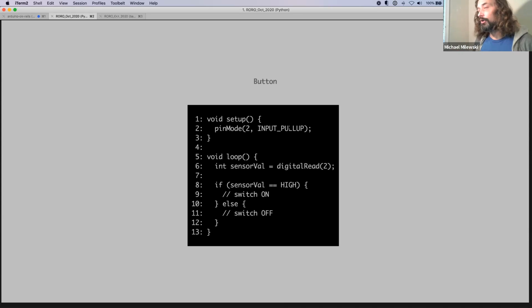To stop that, you want some resistance in there. So the resistance reduces that. In this case, there is inbuilt resistance. So you can really simplify your circuit. So the circuit I've got literally just has a button. It doesn't even have a resistor. It doesn't need that. So that's one thing that's happening here. There's an internal pull-up resistor just to make the platform easier to get stuff going.